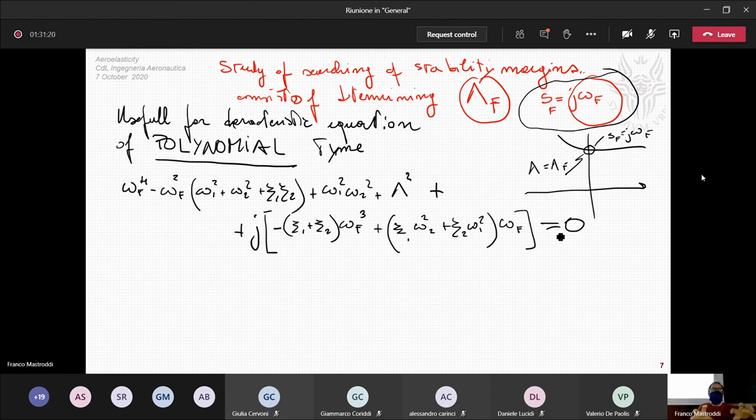So this is an easy case. This is a standard case. You should have solved this exercise in your past control theory course. No problem. Because in control theory course, you study only ordinary differential equations, essentially, regulating and describing your system. So in this case, this is a method which is quite acceptable for analytically determining your margins for stability. What about your margins? So the margins are represented by lambda flutter and the frequency of the oscillation, of the unstable oscillation.